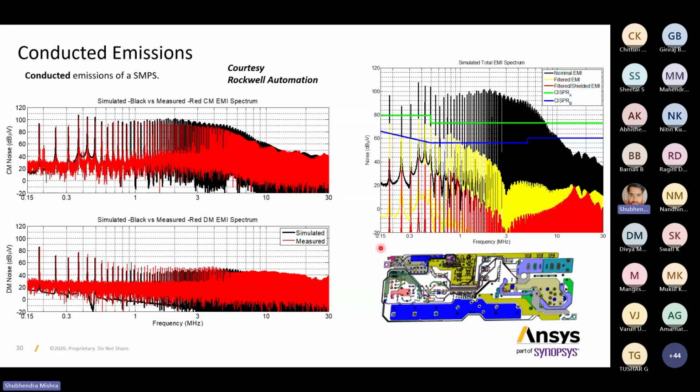and common mode both. Now I have got the noises, so how do we limit them? Just for example, this is square A and this is square B. For square A, there is a limit line. Whatever noises we get above that limit line are our unwanted noises, not included in the simulation phases. So make some changes and evaluate again. Our target is to get all the noises below this limit line for the whole